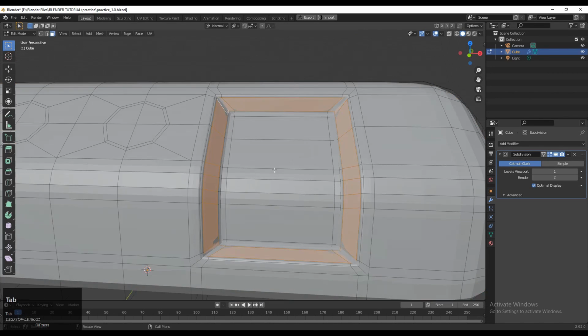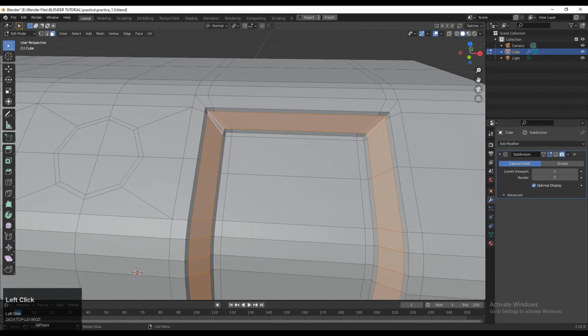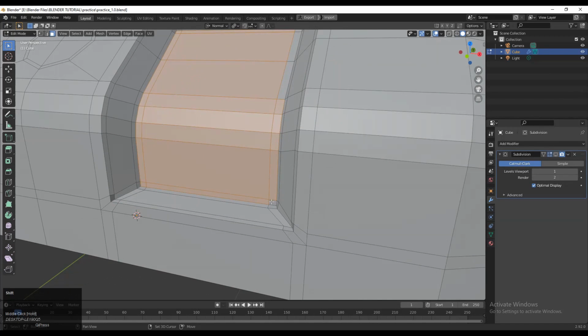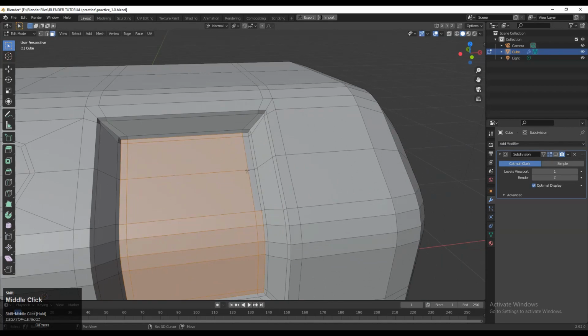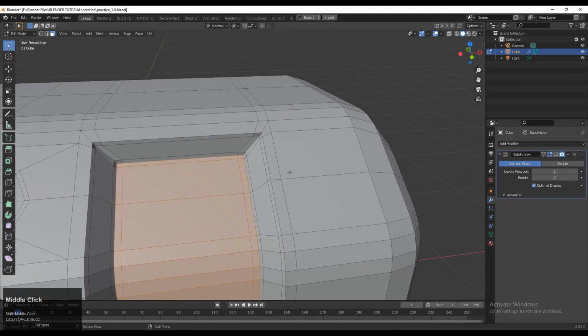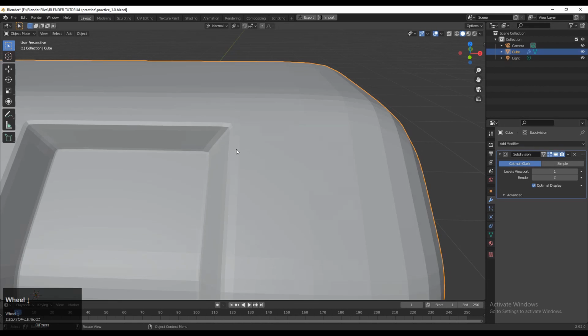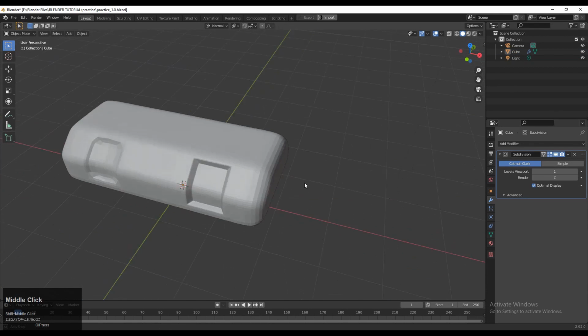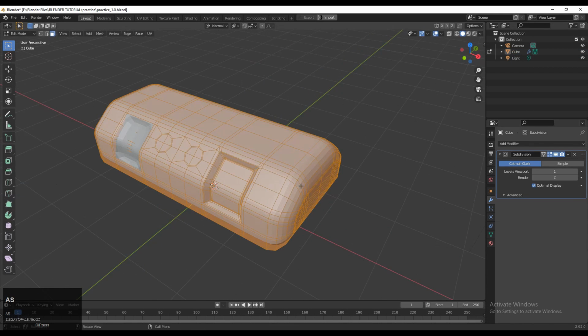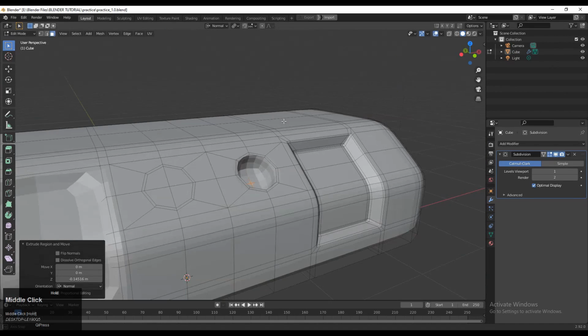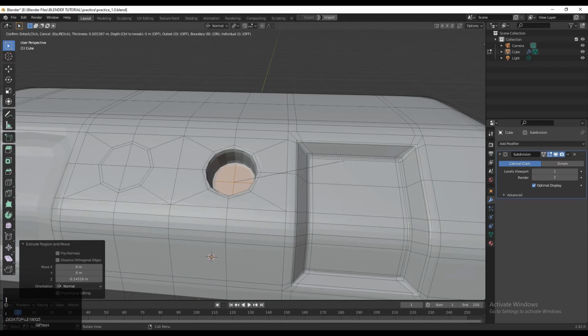Then select these faces, press I for the insert operation just to add a few more loops there. Then you need to select these faces. So you can use shift, select these faces. Simple steps. Nothing complex is there. Just you need to understand the topology and the designs. That makes a difference. Okay, after using the insert operation, now you can create a little bit of boolean structure here. Simple, not complex.